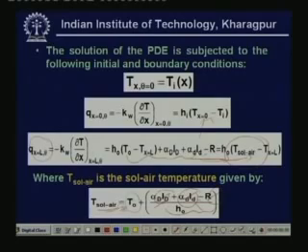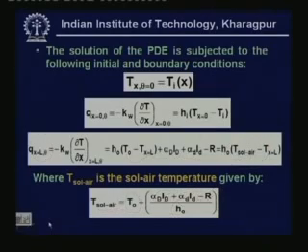And you can also see here that the sol-air temperature depends upon the outdoor surface conductance h_o. Okay. So the advantage of defining the sol-air temperature is that you can write the outdoor boundary condition as h_o into (T sol-air minus T wall temperature). Okay, so the form looks simple, but the sol-air temperature depends upon several factors like the radiation, solar geometry, and the outdoor convection and all that.